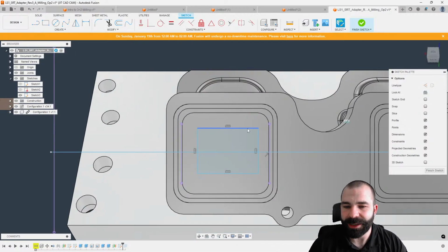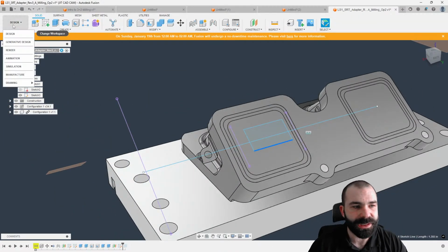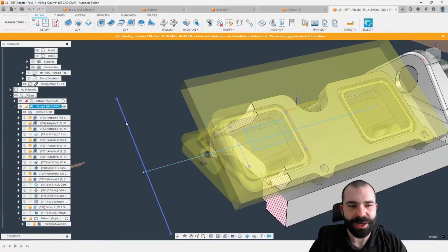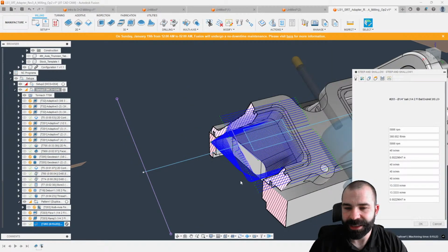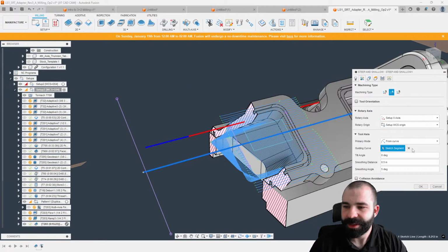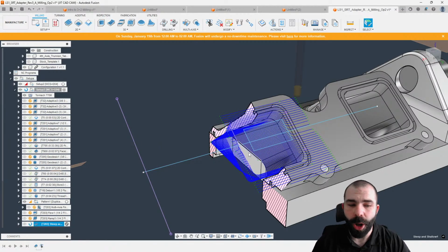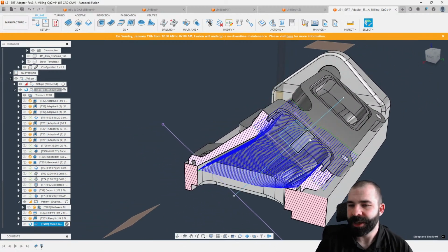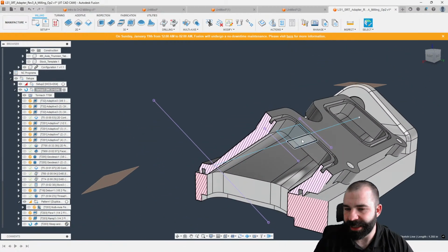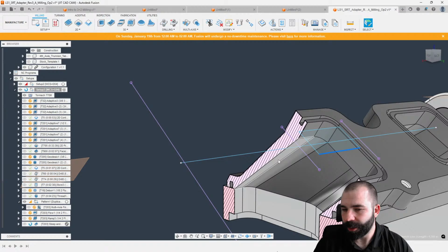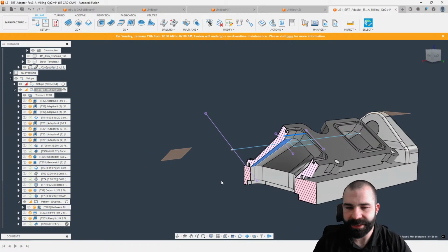Now, keep in mind, Fusion is going to maintain the distance shortest to shortest, right? So whether it be a rectangle or a circle, when I'm manufacturing this, it doesn't make me a liar, hopefully, today. Fusion wants to keep your tool from that line, the wall, in the shortest distance possible, right? So it's not going to ever go from this line here to this back wall, right? It's always going to maintain that from this line, and that makes sense.